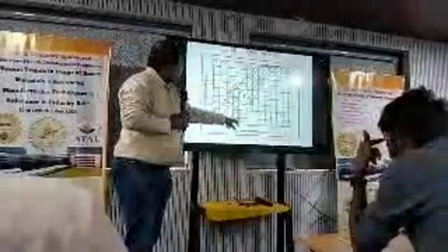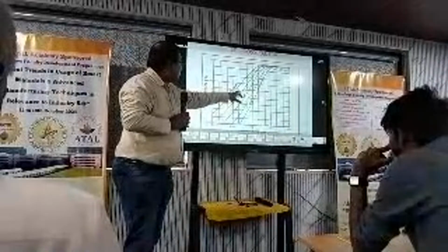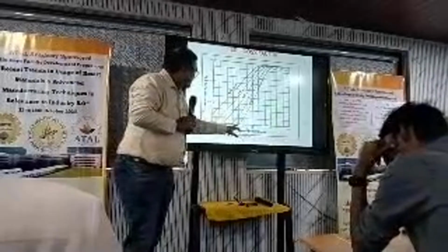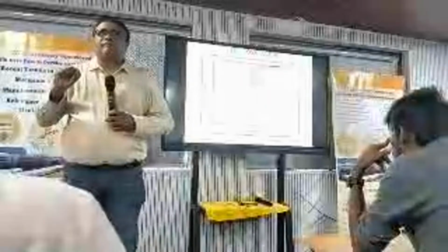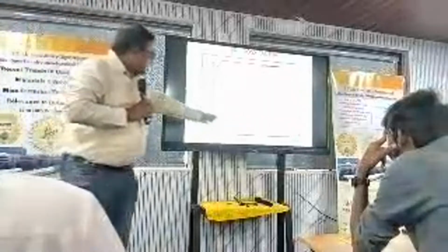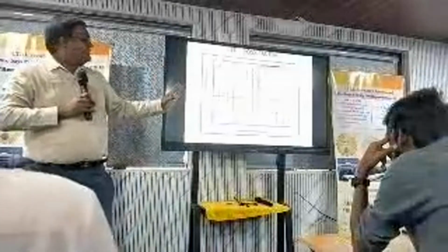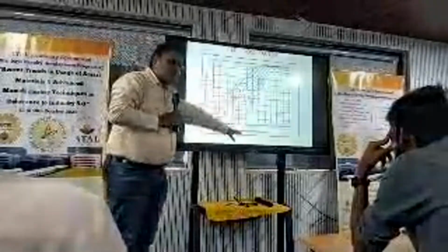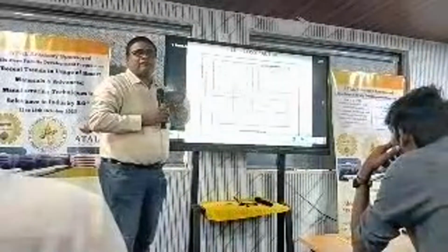After that, you have to find out the thickness ratio. Let us assume H2 by H1 is 1, or this is 0.2 or 0.3. Like that, you have to select the thickness of the material. The bottom layer and viscoelastic layer thickness will be either 0.1, 0.2, 0.3, 1, 2, depending upon the required isolation. Like this, you have to find out the modulus and thicknesses depending on the required isolation. Higher the isolation, better for us.